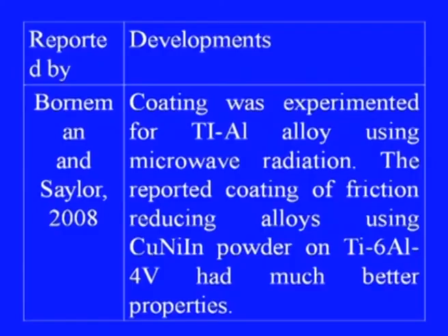Then another work was reported by Camerota and his co-researchers. They irradiated titanium substrate with nickel aluminum powder to obtain a nickel aluminum coating, and they could obtain good results on titanium substrate.